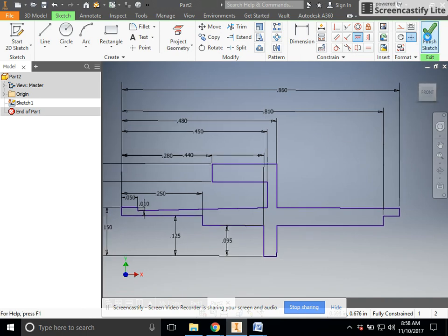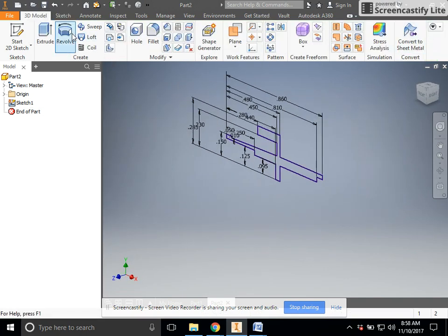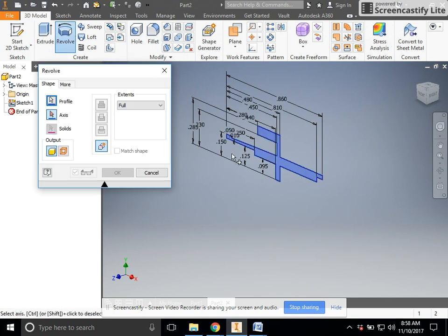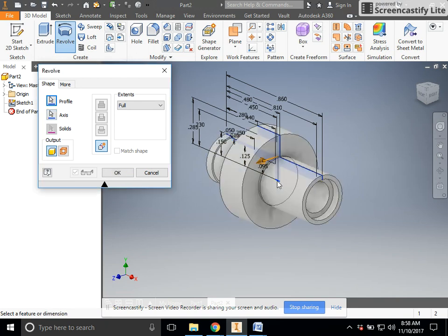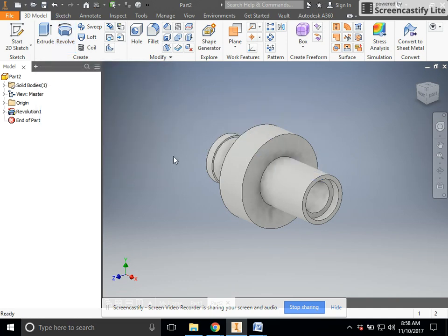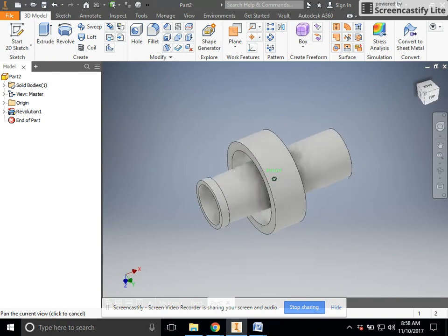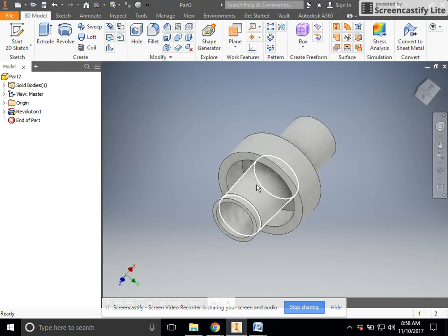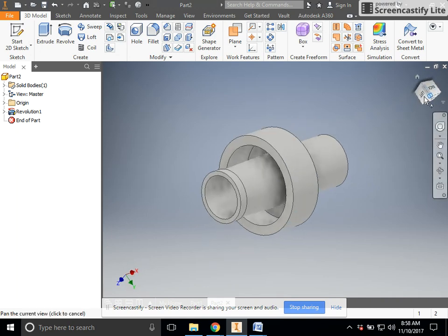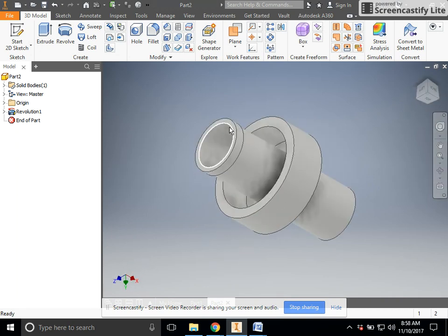We're going to finish the sketch and use the revolve tool. So using the revolve tool, it already automatically selected our profile, so it wants to know the axis. So here's the axis. And that looks all nice and neat. Hit OK. And I've got most of the axle done. Now the last trick is to get those 2 little slots in here. And the slots are rectangles that are 0.04 inches wide by 0.2 inches long.